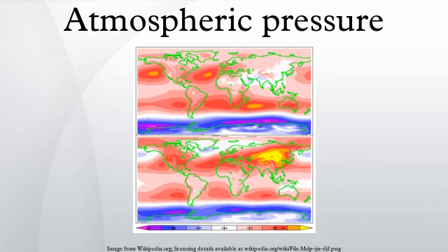At low altitudes above the sea level, the pressure decreases by about 1.2 kPa for every 100 meters. For higher altitudes within the troposphere, the following equation relates atmospheric pressure P to altitude h, where the constant parameters are as described below. Local atmospheric pressure variation.